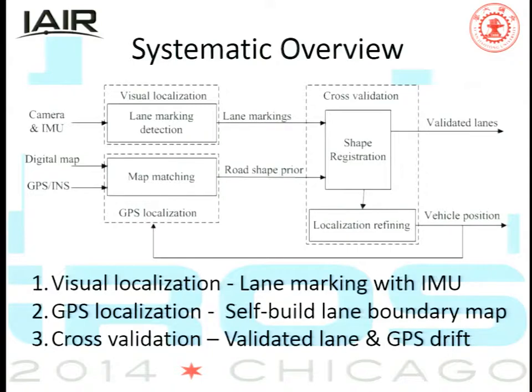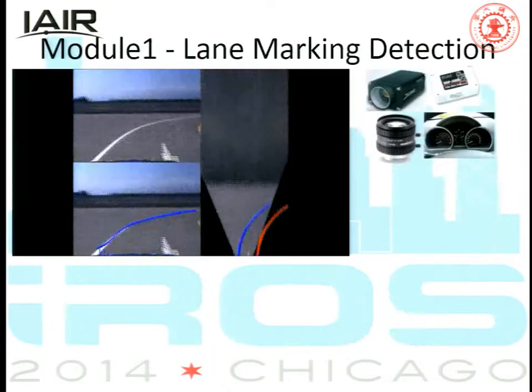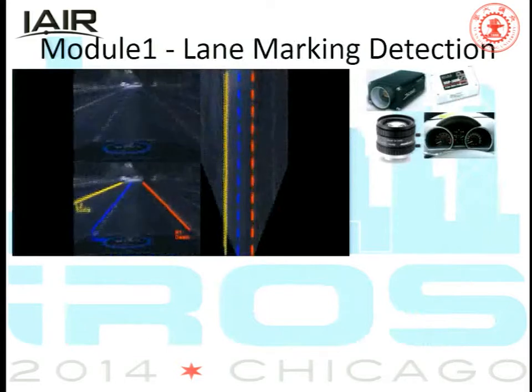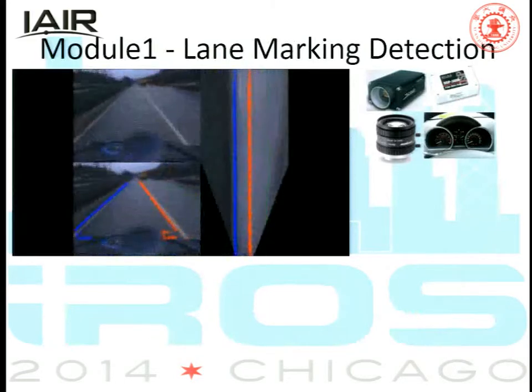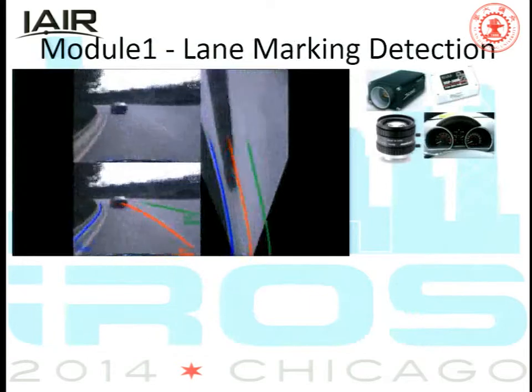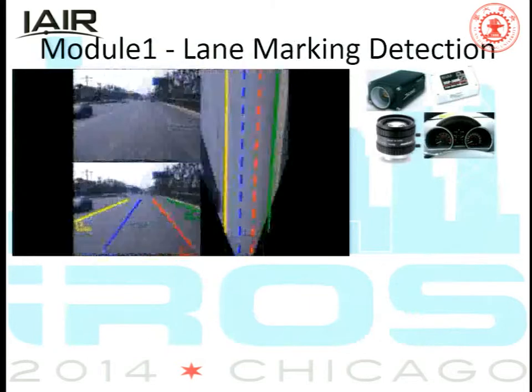The authors adopt a 3-lane model for assigning the semantic attribute for each detected lane marking. The lane marking system provides a stable and robust multi-lane marking detection with a local localization accuracy of centimeter level. Lane marking detection is performed by integrating vision-based detection of lane markings and camera pose with IMU.